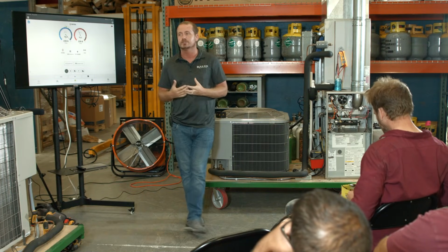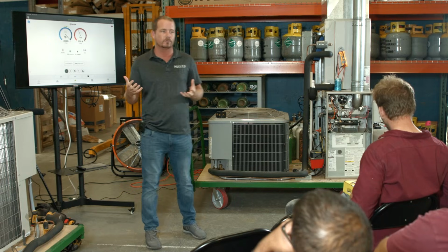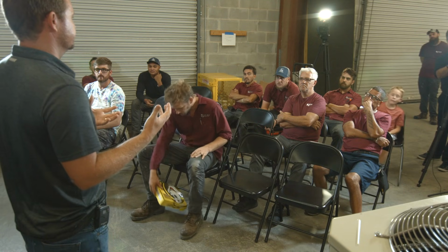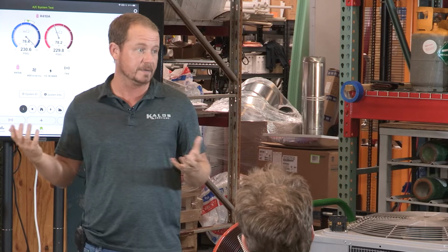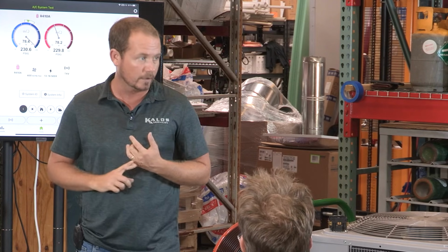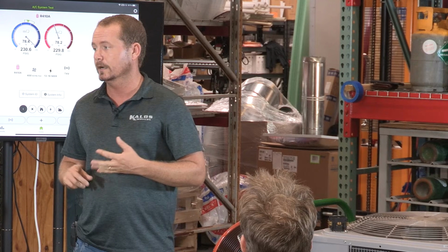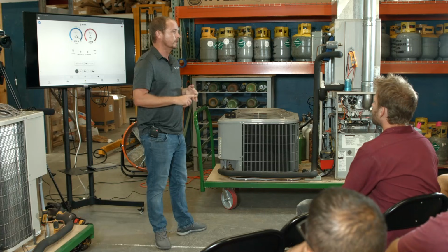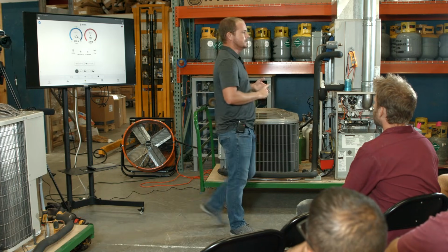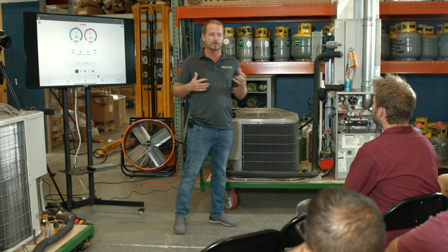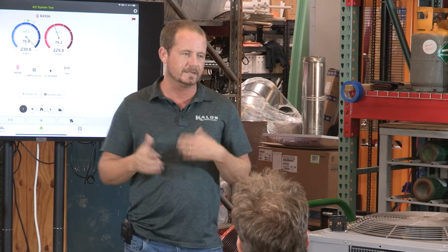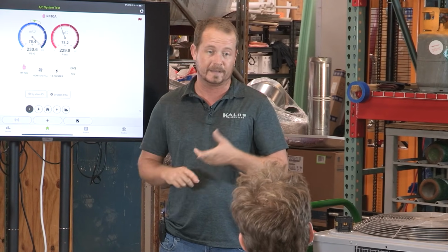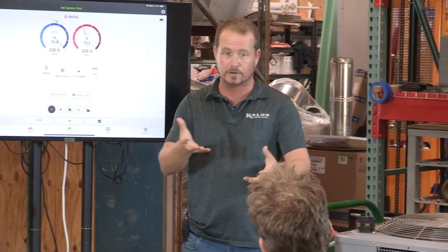First, before you even check static pressure, though, what are you going to look for? Restrictions, right? You're going to look for the things we just mentioned. Starting with air filter, obviously, then going to evaporator coil. You're also going to look at the blower wheel, but blower wheel loading doesn't make the motor function in the same way as other airflow restrictions. We won't get into that right now, but it's not going to necessarily cause that problem. But then you look at things like Bert said, you look at the returns.